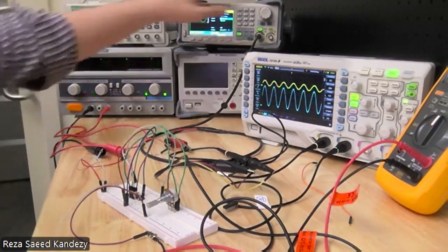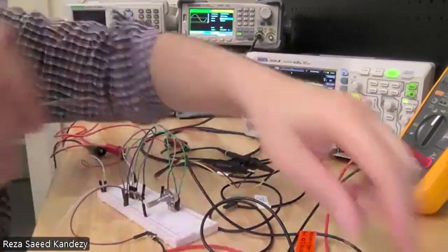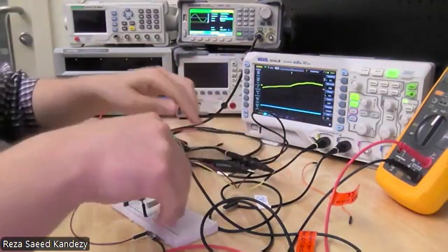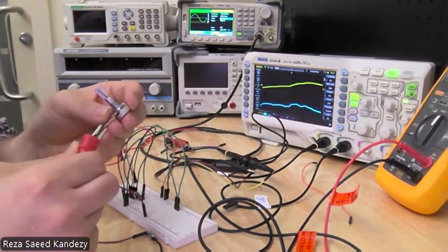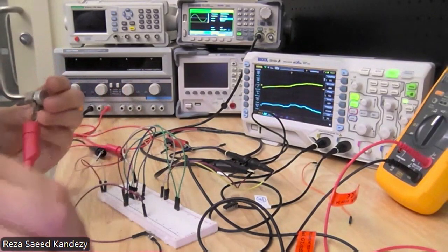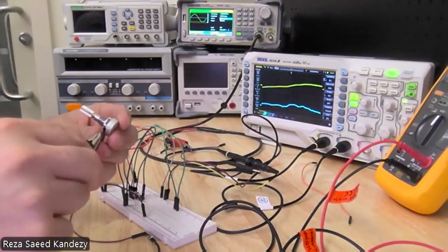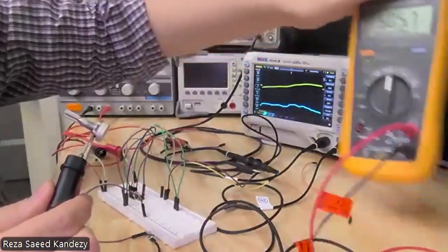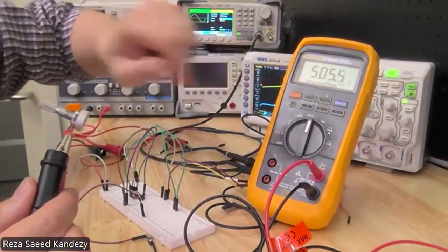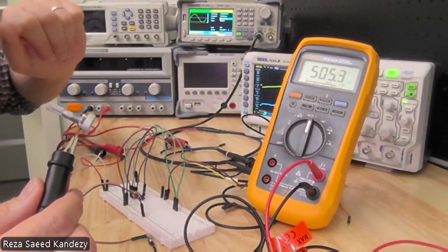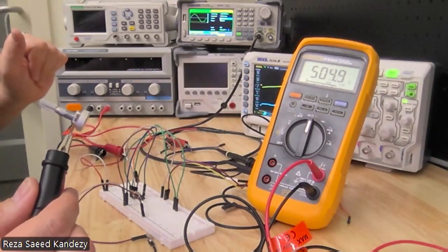Now let's measure. I am gonna disconnect my potentiometer, and I am gonna see what's happening. Okay. What's happening in my potentiometer? Now, as you can see, right now my potentiometer is at 505 ohm. Close enough. We needed 510. But 505 is giving us the amplitude gain of 4.